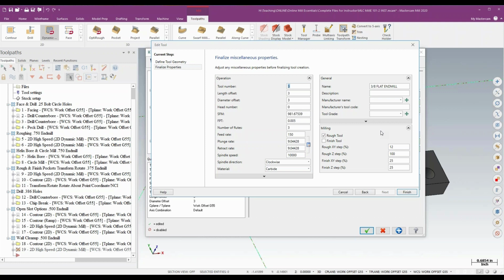It's a very, very simple thing to do, especially on a tool you've been using a lot because you know what you're going to run it as. I don't have to go look it up. I don't have to go find my notes or the post-it note that I scribbled it down on what I was going to run it as. It's there on that tool and it stays that way. That tool's in a database. Once I change those, whenever I decide to grab that specific tool, I'm going to get those values to auto-populate on the toolpath that I'm using. It's a small thing, but it's a huge time saver, because how many times have you been digging around trying to remember what you were supposed to run something at?